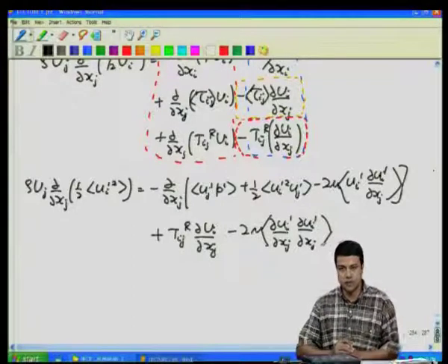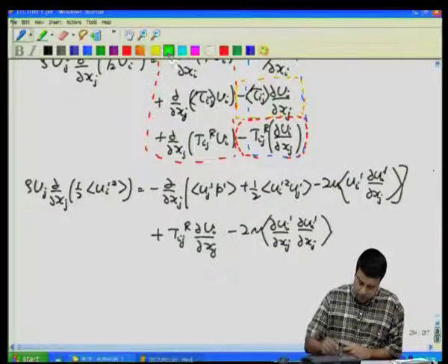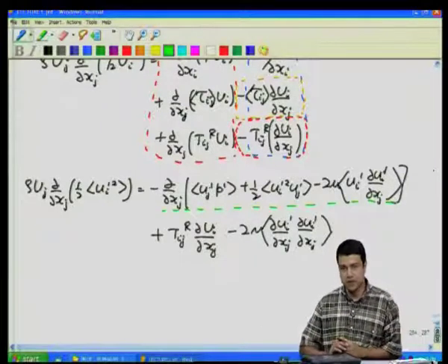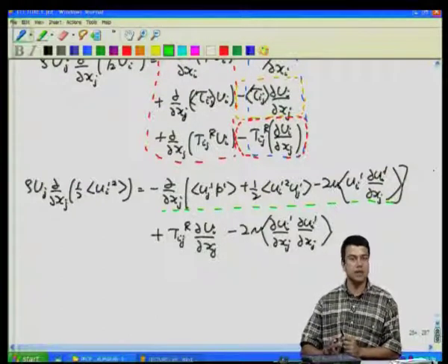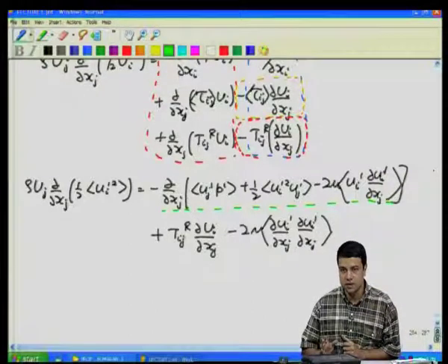So, that was the energy for the turbulent kinetic energy fluctuations. The first terms that you see here are of course just the divergence of something, and if you write that down for a surface for a particular volume, this converts into a surface integral and just represents the exchange of energy between adjacent volumes.